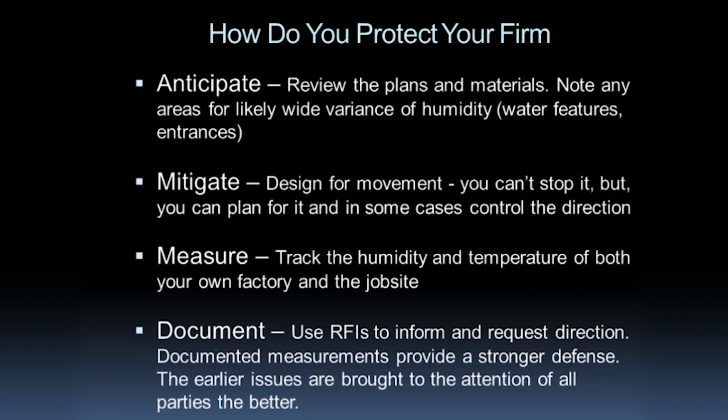The thing to be cognizant about, I think, is that there's a different time frame for unfinished woodwork and pre-finished woodwork. Pre-finished woodwork is going to take longer to acclimate. I think the 8th edition quality standards said a week or more, which can be very tough given today's construction schedules, but just putting that out there.